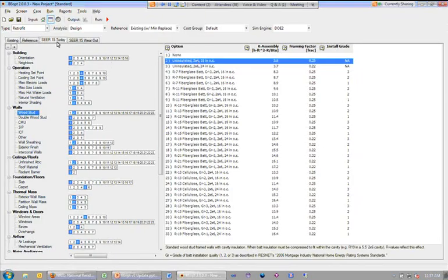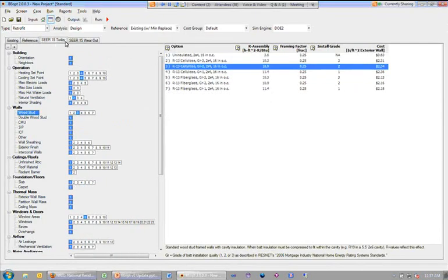Therefore, when I look at some of my post-retrofit situations, I only get presented with wall types that are also 2x4. This is filtered automatically by the measures database, and therefore we get this relationship information as well in BEopt. So it helps to tailor our interface so that we don't show 2x6 walls when you started with a 2x4 wall.